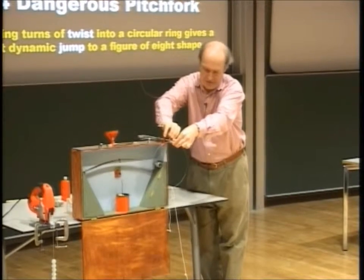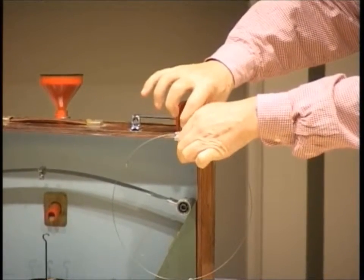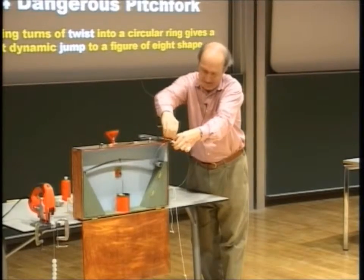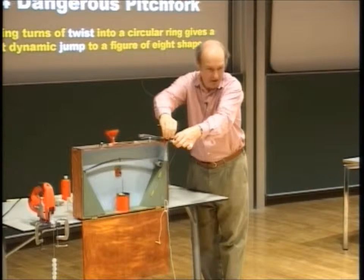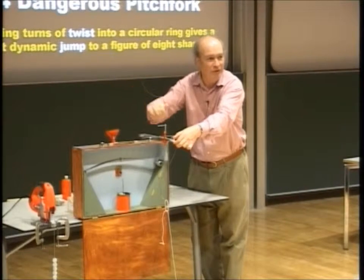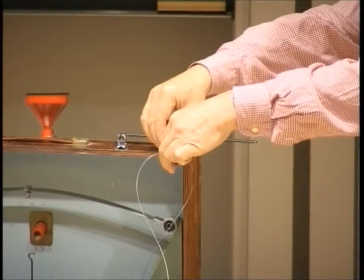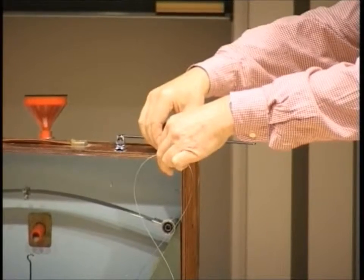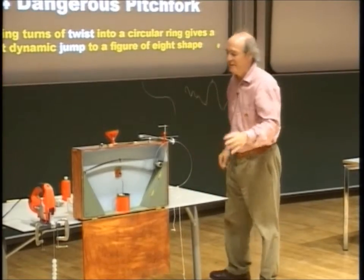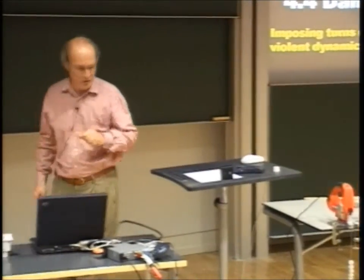And because it's a dangerous bifurcation, we expect things to happen fairly suddenly. Quite hard work twisting this. Okay, it's jumped into a figure 8. And it jumped suddenly. It didn't sort of hang around. It was a dynamic jump. It went to a new solution. If I unload, nothing happens for a little while. It stays where it is. Then it gives one little flick out. And then if I unload further, another flick out. And of course, this happens in DNA, and I shall be talking about DNA a little bit later. So that's an example of a dangerous bifurcation where you get a sudden jump.